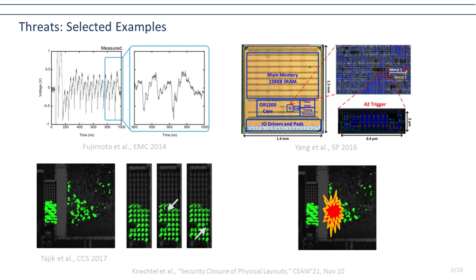Such observations can be made by an adversary in the field, and they can be well correlated with sensitive computation, let's say some cipher operation, and accordingly sensitive data like a secret key can be inferred. These kinds of attacks are called side channel attacks, and this particular one is called a power side channel attack, which is quite advanced and quite helpful for an adversary to infer secret data.